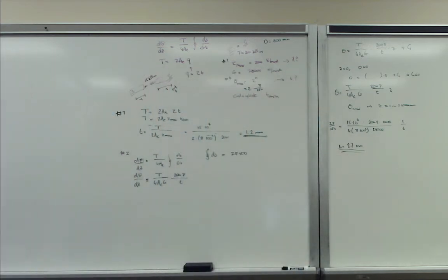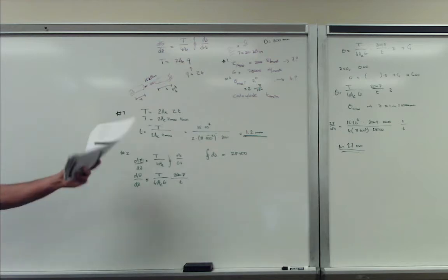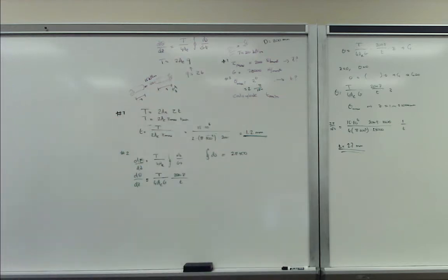So this becomes important with torsion. Often with torsion problems, the stresses are not necessarily the issue, but rate of twist and the twist angle will be. So you have to keep in mind that for a given torsion problem, you have to double check, especially when you're given the question, what's the minimum or maximum stress, or what's the maximum deflection. You have to check all the requirements given.